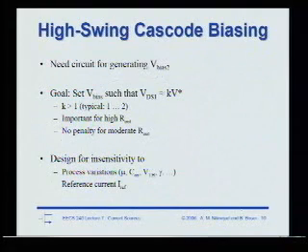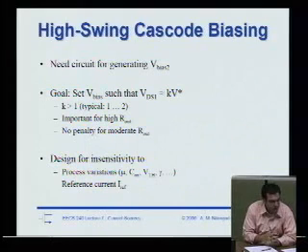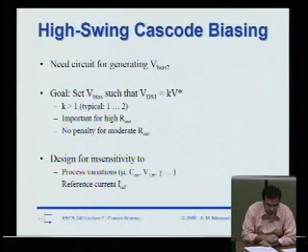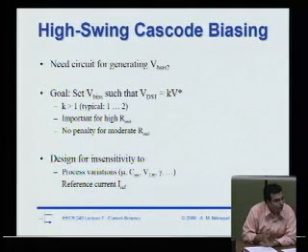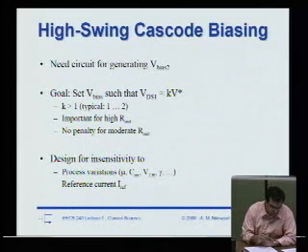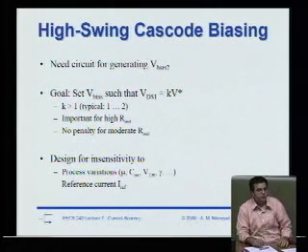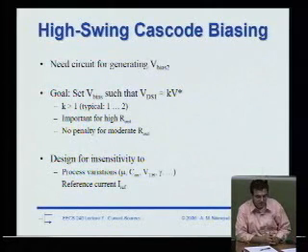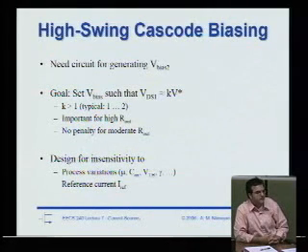Okay, so the problem now is that we know that we can solve the headroom problem, at least to some degree, by biasing up the gate of our cascode device through a custom voltage. That custom voltage needs to have basically overdrive voltages in it and VTs in it. So why not just plug in a constant voltage there, right? Figure out with SPICE what the overdrive voltage is, what VT is, and just plug in K times VT plus 2 overdrive. Why not do that?